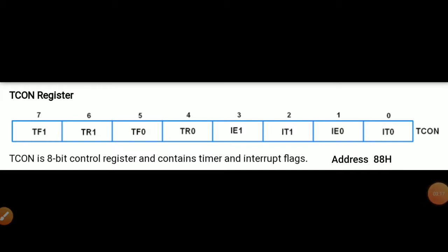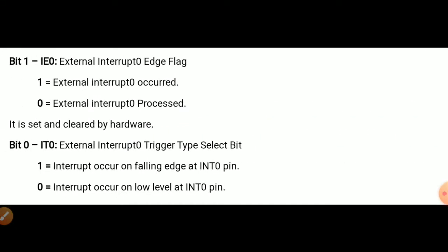The TCON register. The lower nibble is for two external hardware interrupts, IT0 and IT1, wherein the bit 0 and bit 1 represent the interrupt 0 bits.